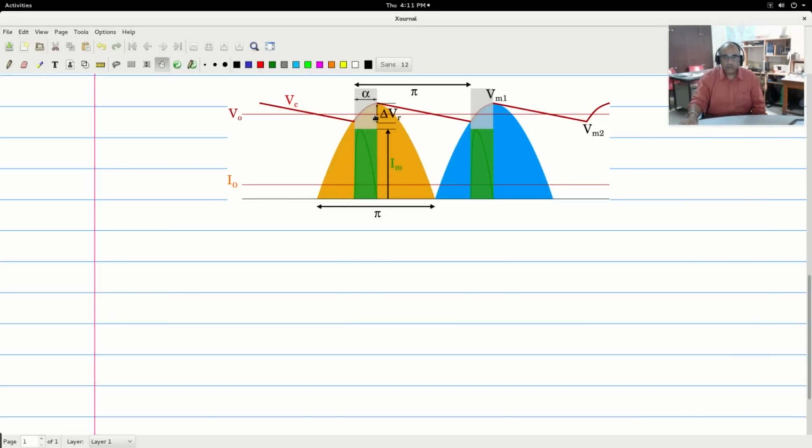Let us start at this point. Let us see what is happening at this point, or shall we come down here, to the corresponding point. At this point, the capacitor has an energy half C Vm1 square. And from here to here, the diodes are off. Likewise here, from here to here, the diodes are off. The capacitance is doing only the job of discharging into the load.